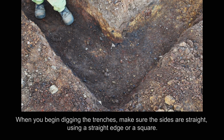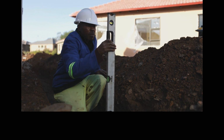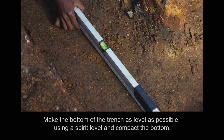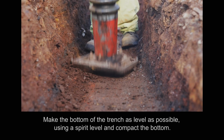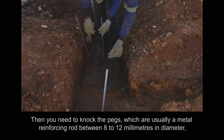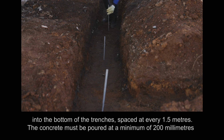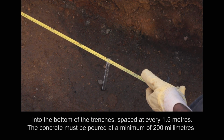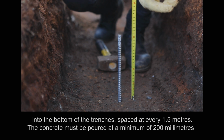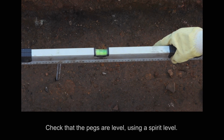When you begin digging the trenches, make sure the sides are straight using a straight edge or a square. Make the bottom of the trench as level as possible using a spirit level and compact the bottom. Then you need to knock the pegs, which are usually a metal reinforcing rod between 8 to 12 millimeters in diameter, into the bottom of the trenches, spaced at every 1.5 meters. The concrete must be poured at a minimum of 200 millimeters. Check that the pegs are level using a spirit level.